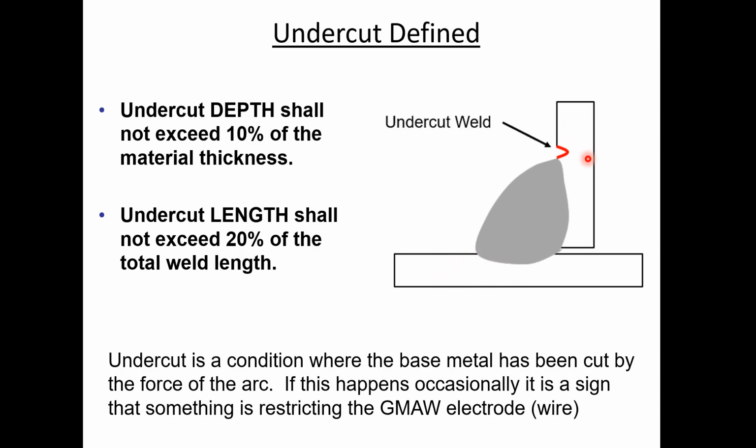And we heat treat them when you get them hot, and then the volume of heat in this keeps coming. It keeps coming. And that's the recipe to soften material. When you keep a material hot, keep it hot, keep it hot, that ends up making this material softer. The grains grow, and that's not doing us any good, because this confined and small area, now this heat that's being dumped out is confined into a smaller area.